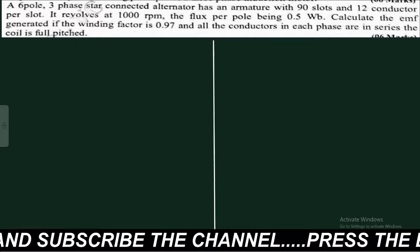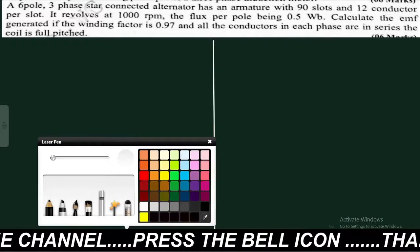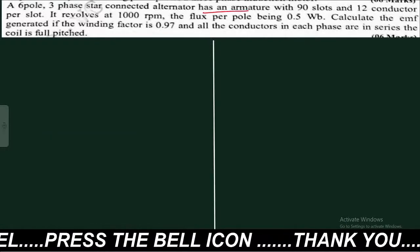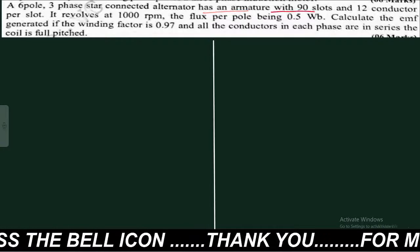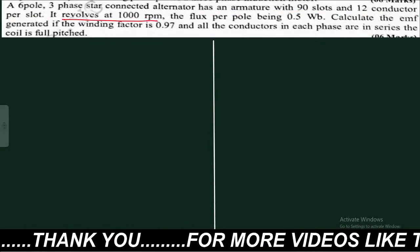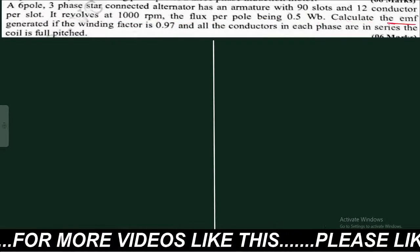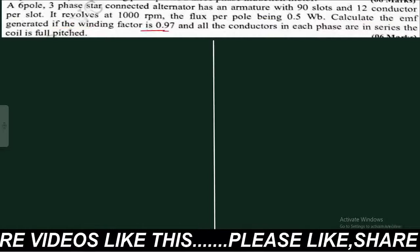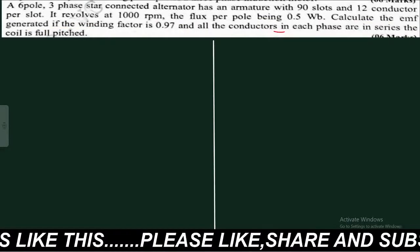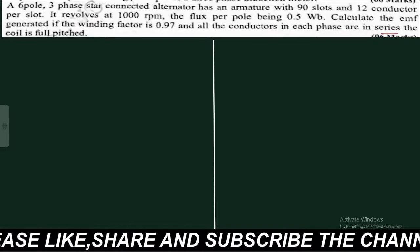A 3-phase 6-pole star connected alternator has an armature with 90 slots and 12 conductors per slot. It revolves at 1000 rpm. The flux per pole is 0.5 webers. Calculate the EMF generated if the winding factor is 0.97. All the conductors in a phase are in series, and the coil is full pitch.